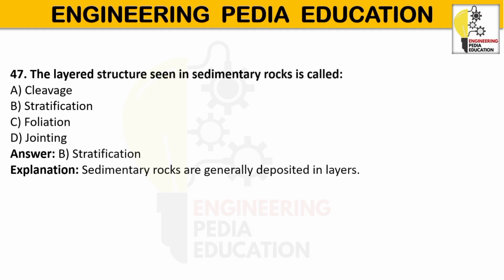Stones should be laid in construction with their natural bed horizontal. Loading perpendicular to the bedding plane provides better strength and durability. Stratification is the arrangement of sedimentary rock in distinct layers or beds formed during sediment deposition. Which rocks commonly show stratification? That is sandstone and limestone. Sandstone and limestone are rocks which mostly show this stratification.